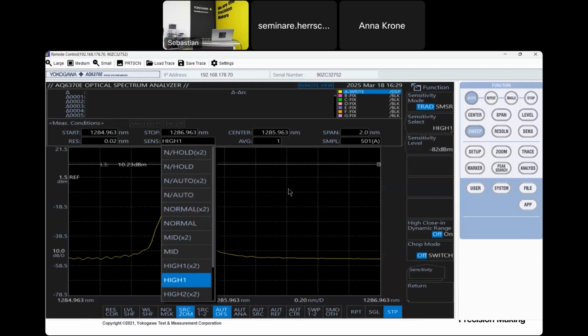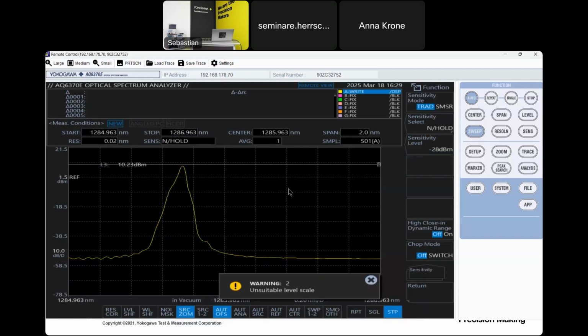And as we see, a repetition period of 100 microseconds is the same as 10 kilohertz, which is much below the 10 megahertz that we were given for the frequency, so we do not need to take any extra considerations.